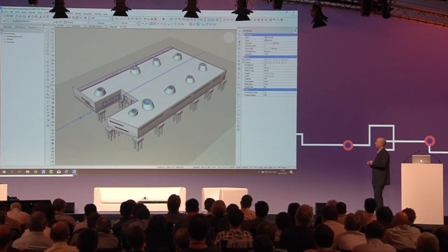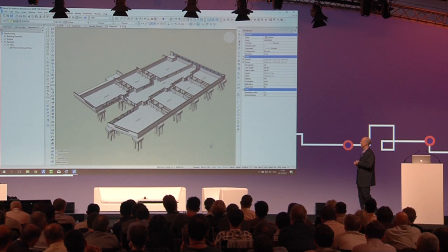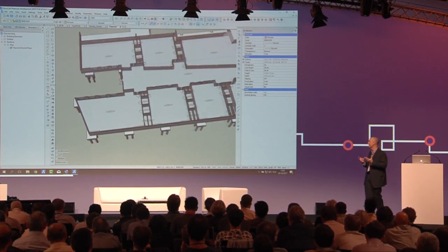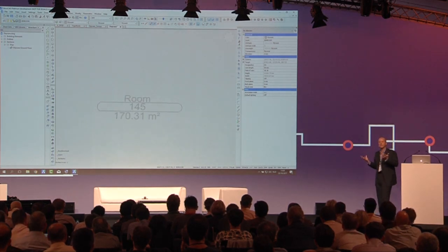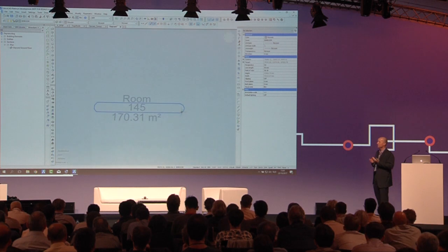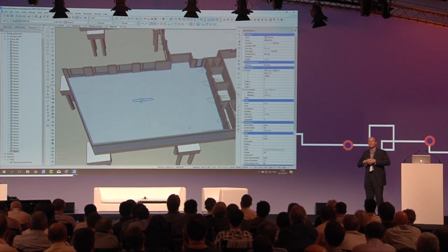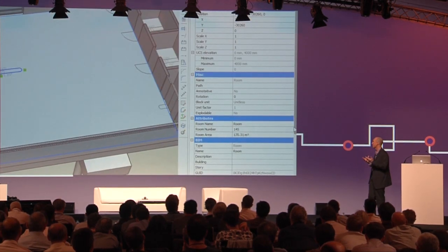So in this case, let's see what the state of the drawing is that we just activated from the overall BIM. If we look around, it appears that all the rooms have been created already. And when the rooms are created, they get a default room tag that has the room name, a sequential number assigned, and an area. And you can change those values if you want. You can change the shape of the tag if you want as well.